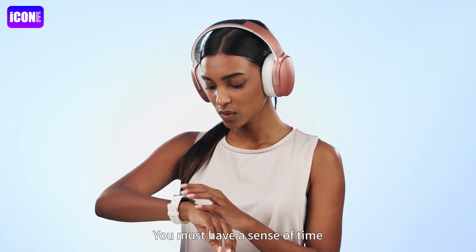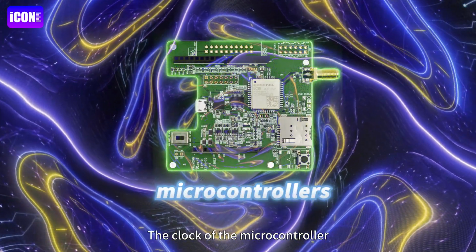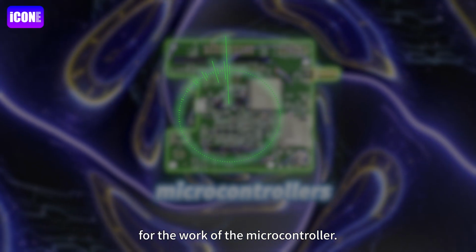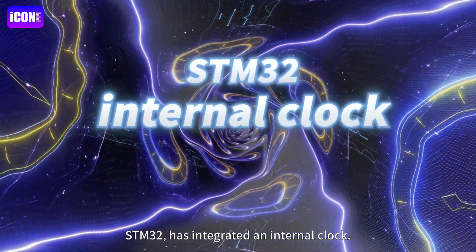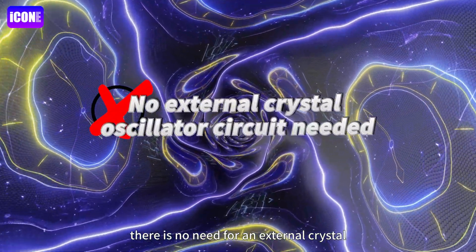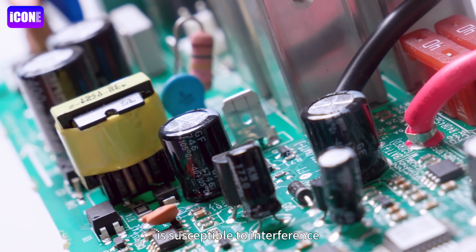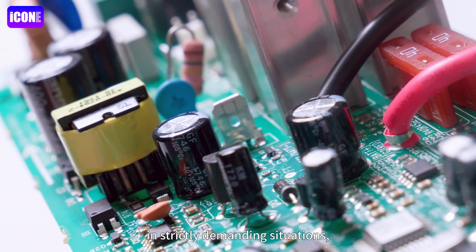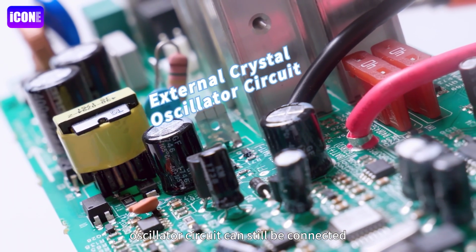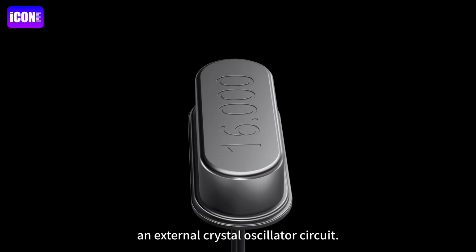You must have a sense of time to keep your lives in order, and the same is true for microcontrollers. The clock of the microcontroller is the rhythm required for the work of the microcontroller. STM32 has integrated an internal clock, so in general applications there is no need for an external crystal oscillator circuit. However, since the internal clock is susceptible to interference from various factors, in strictly demanding situations, an external crystal oscillator circuit can still be connected when needed. The system clock usually adds an external crystal oscillator circuit.